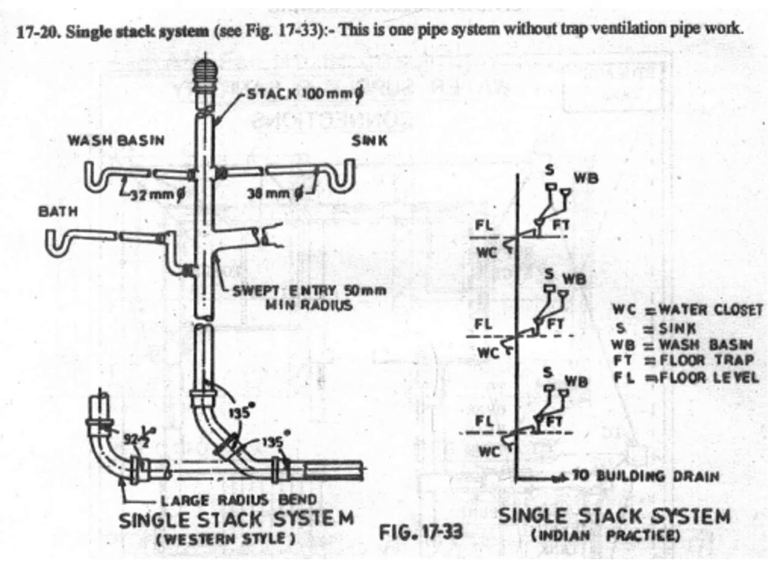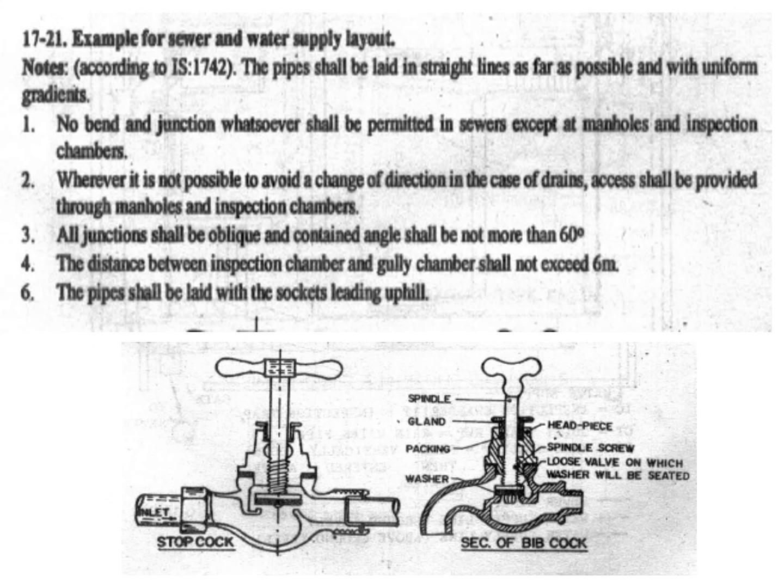Again, these are some different arrangements for single stack systems. That is normally adopted in most multi-story buildings to reduce the amount of pipes, for economical as well as space reasons. So these are the collection of wastes from wash basins or water closets, and the same pipe is projected vertically. It is open at the top, where we allow the free movement of air. This is an example of a sewage system or water supply layout.